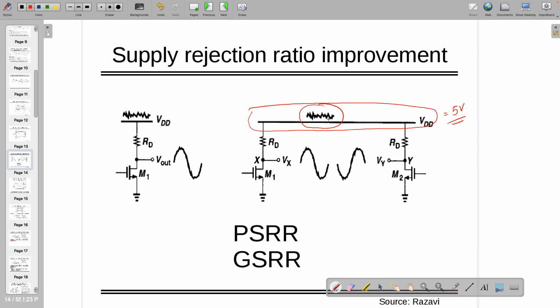If you zoom in, you see that there is some noise, right? Generally it's 50 hertz noise. I'm writing 50 hertz specific to India because it's 50 hertz in the line, right? It might be 60 hertz, which is written in most of the books. They call it 60 hertz interference, right? Because that is the frequency of the one you are converting from AC to DC. So this is actually DC.